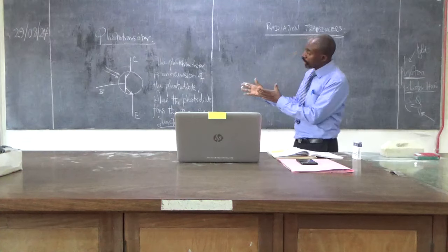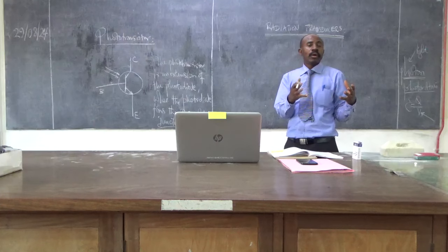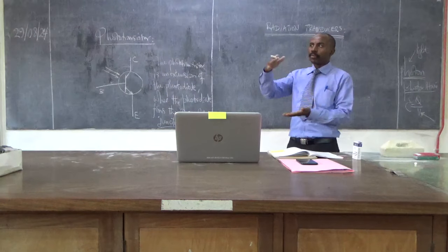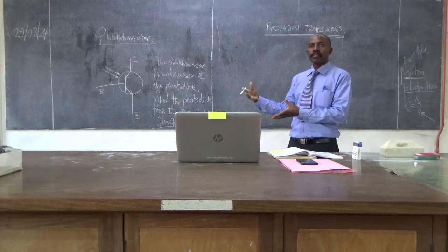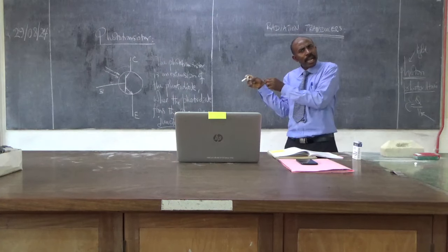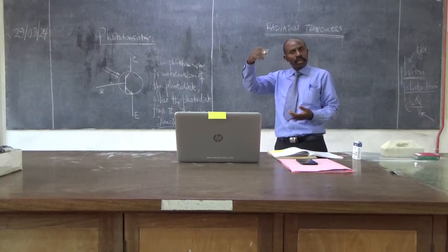So you have a photodiode, you now can arrange your potential divider, and once you have put your potential divider, then you make an amplifier and amplify what was a very tiny current produced by a photodiode, then you amplify it to a huge output.